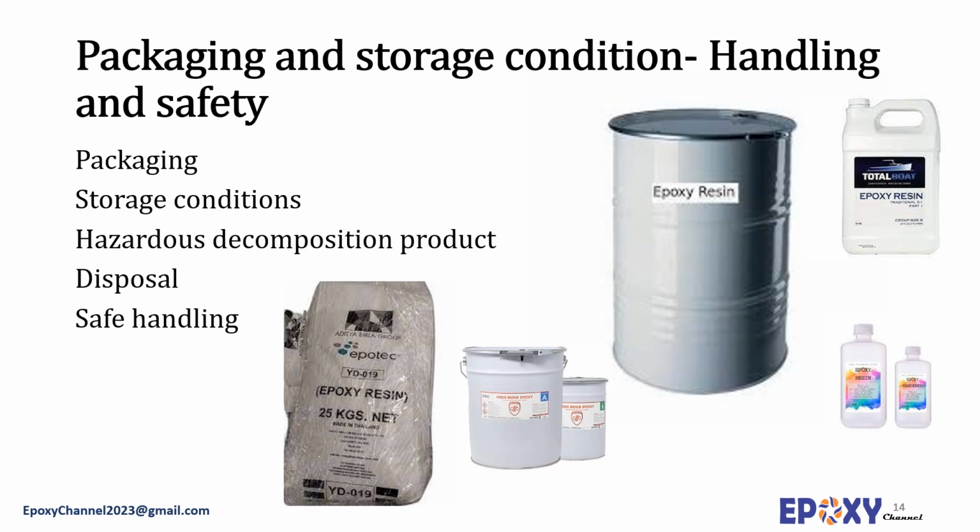Hazardous decomposition products are the components released when an epoxy resin is burned in a fire. Here again, the type of released product is mainly dependent on the structure of the epoxy resin, but generally speaking, carbon monoxide, carbon dioxide, or other toxic gases and vapors are common when the epoxy resin is put on fire. Under the disposal section, guidelines for the safe disposal of cured and uncured epoxies are presented. Often, the TDS and SDS documents refer the user to the regular procedures approved by the local authorities.